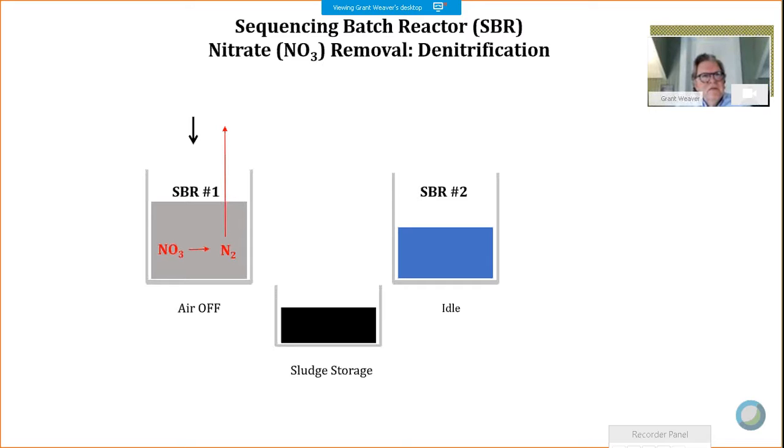So if you have an SBR, or if you're operating a facility to be like an SBR, you're looking for those environmental conditions when you have a good aerobic environment and a solid anoxic environment. And the transition time is not wasted time, but there's a lot less beneficial activity happening during those transitions.